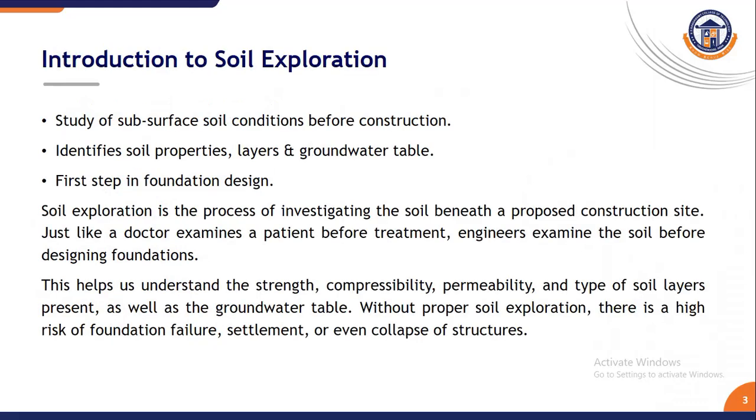The first topic is the introduction to soil exploration. Soil exploration means the study of subsurface soil conditions before construction. It helps us identify the soil properties, soil layers and groundwater table. It is just like a doctor examining a patient before prescribing treatment. Engineers must examine the soil before designing the foundation. Without soil exploration, there is a high risk of settlement or even failure of the structure.